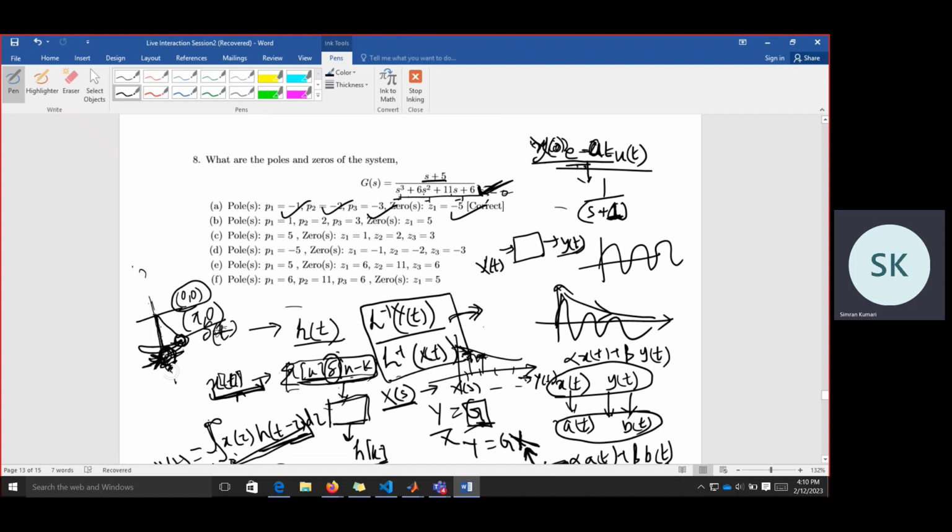So if it settles to equilibrium, we say that it has come to its equilibrium point. Now it will not evolve from here. So this is a stable equilibrium point. From poles we can find whether the system is stable or not, because we know the response to perturbation for a linear system. And since this is a linear system, this will be the global response. It's not a local response, because for a linear system we are linearizing at this point.